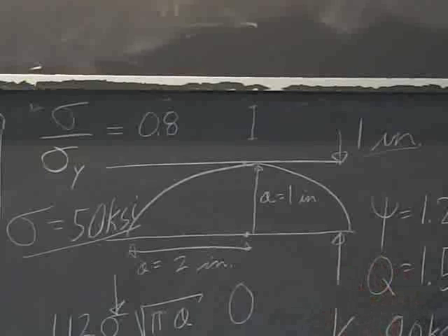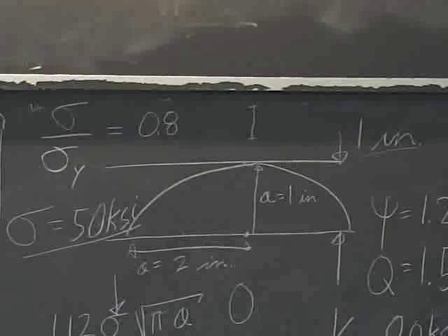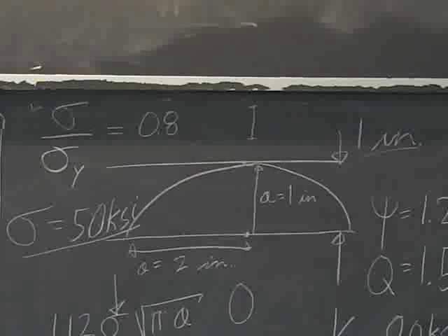So if what you're thinking about is safety, and weight, for example, is not so much of a concern, it's obviously going to cost you more to make it out of a mild steel, but if you can avoid a catastrophic failure in some situation, it's worthwhile, and that's why they do it. So you end up with probably twice as thick of a wall, but it's still going to leak before breaking, as opposed to leading to a catastrophic failure.